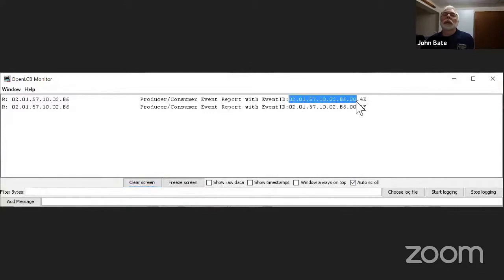I'm going to be saying a lot of things that boil down to ignore that. That little thing at the end, there's the event that it produced when I did that. LCC nodes typically come with everything automatically connected as an input and automatically generating two different events, one when the input goes high, or 1, or 5 volts, and another when it goes the opposite.